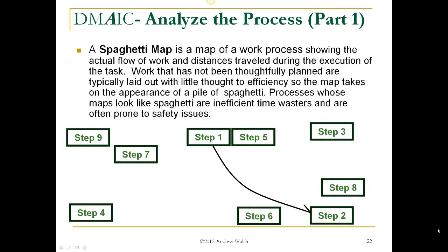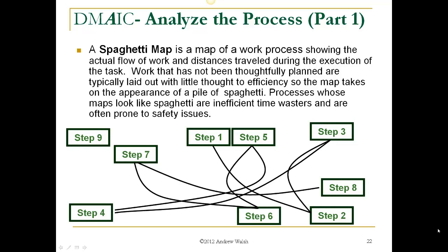And as we see here, we have a number of steps that go back and forth and cross over each other. So step 1 moves over to step 2, jumps up to step 3, goes across the hall to step 4, then comes back to step 5, etc., etc. It may be more functionally efficient to move steps 1, 2, 3, and 4 maybe over to the right and have all those steps done very close to each other, so it's very easy for those inputs and outputs to flow between each other, and then maybe moving over to the left for 4, 5, 6, 7, and 8. That may be a better layout, or it can be broken up into something else, but not a lot of crossover, because crossing over allows for safety issues, as already said, but also allows for the introduction of cross-contamination.